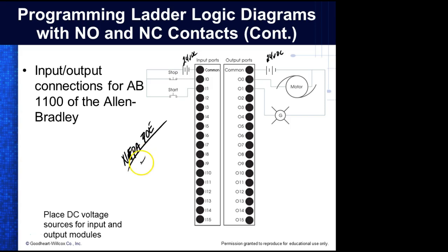They established that anything 50 volts and above is lethal. Anything below that is not lethal. That's what 70E established. So if you're working at a plant and you get into a control cabinet and it's above 50 volts, you've got to start adding to your PPE. What does PPE stand for? Anything below 50 volts is just standard stuff: hard hats maybe, safety glasses, leather shoes probably. It all depends on the company you're working at.